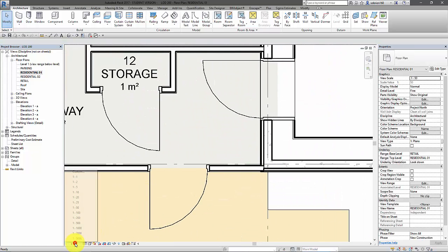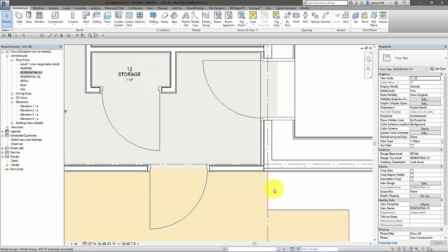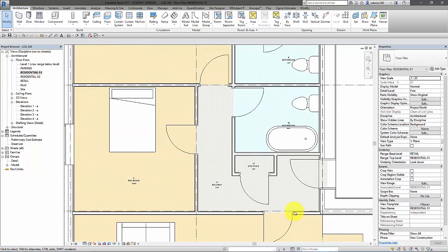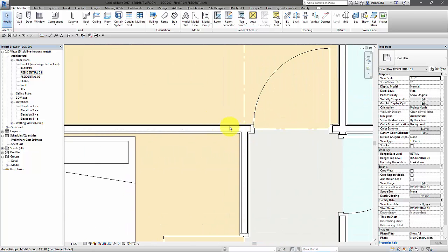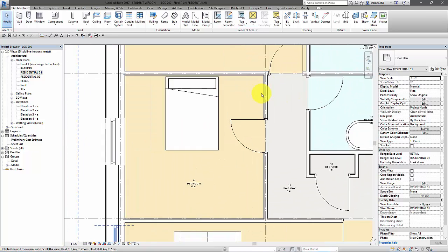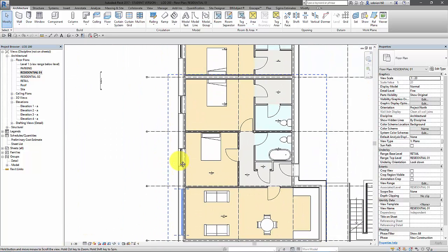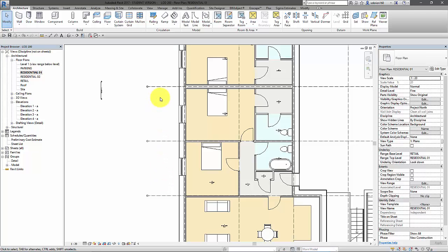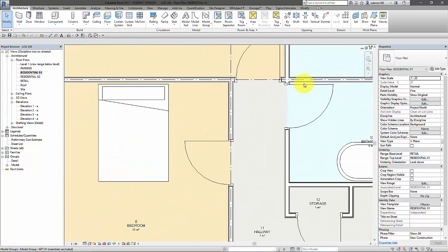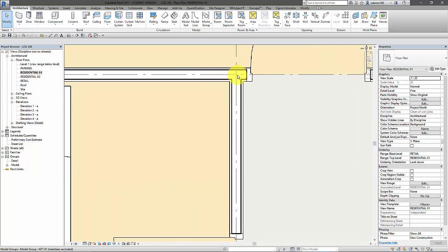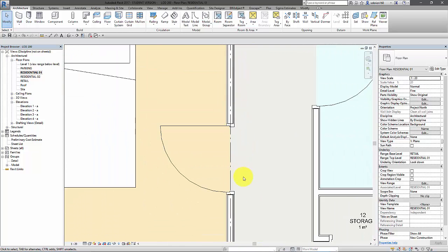The other thing is, if I just turn this level of detail up to 20 here, you can see that initially when I sketched up the apartment here, I just used these modular grid lines as the guideline because they're based on the 300 module. They're 3.75 meters, which if you double up is 7.5 meters, which is divisible by 300. Therefore, it's part of the Western European construction module. So I did that initially, so they follow directly down the core center line of the internal walls here.